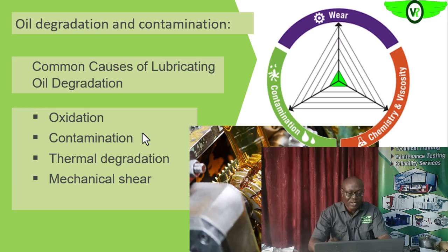Then we have mechanical shear, that is subjecting the lube oil to excessive shear stress. When it is subjected to excessive shear stress like that, the polymer molecules, especially in multigrade oils, will be stretched and at times even be broken, and that will affect the viscosity of the oil.